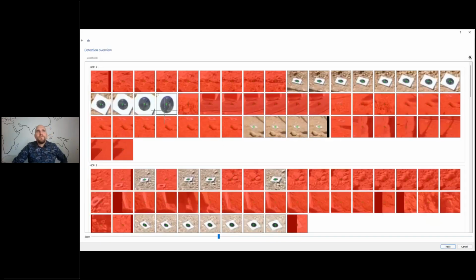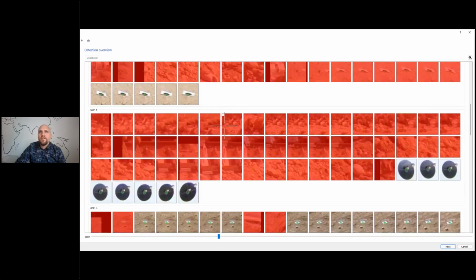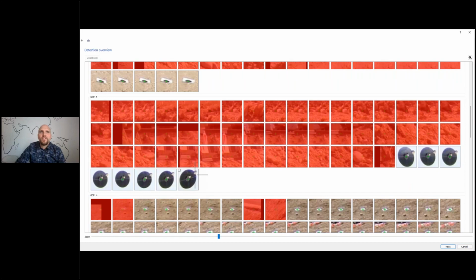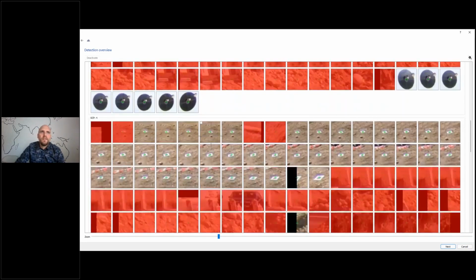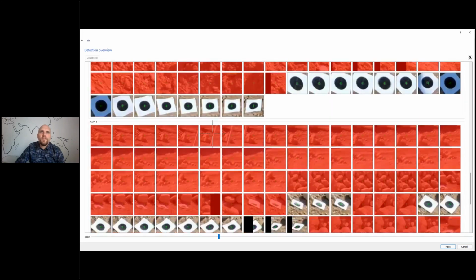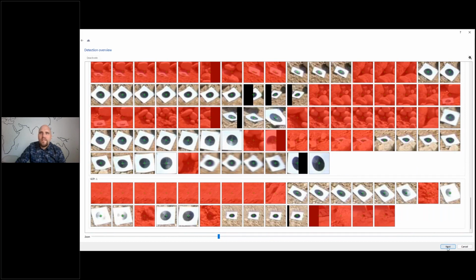So here probably the situation will be you will have some photos from very close by, some will be from further away. So probably here there will be some manual adjusting of these positions. So here it's only important to have each ground control point on, say, between 5 and 10 images. That should be plenty. So this is approximately what I did here. And then you would just press next, and then this data would be added to our 3D model.